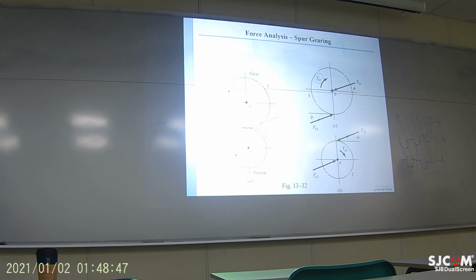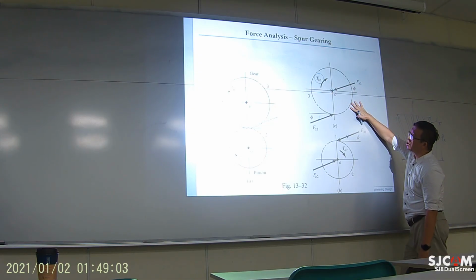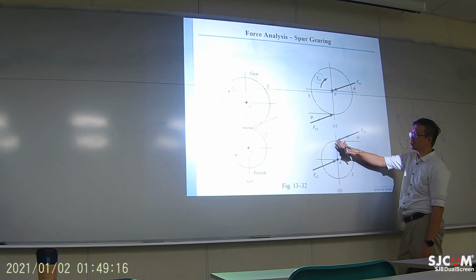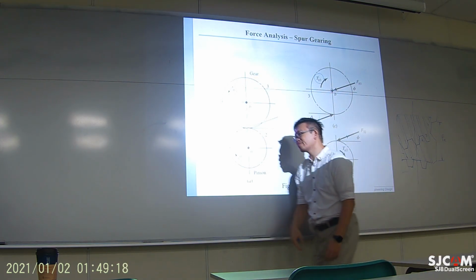But in reality, the entire shaft is carrying multiple kinds of loads, sometimes distributed load, sometimes twist, and complicated. Okay, anyway, that's for the gear side. Similarly, for the pinion side, you also have a reaction torque that is balancing the torque generated by the force couple. Okay?